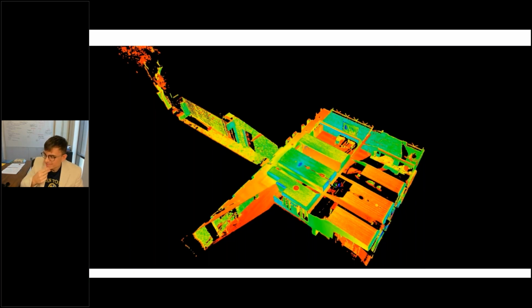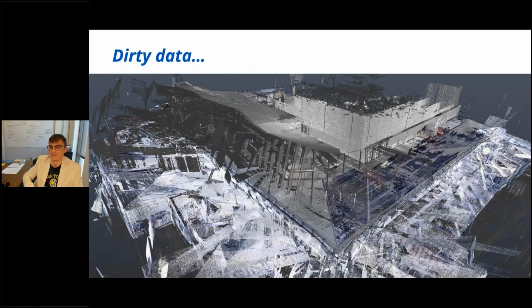And you should know that right now, Recap, a popular software, doesn't allow you to clean scans prior to registration, but pretty much every other software allows for this. And if you're seeing a lot of noise above your facility, you're like, there are no windows or mirrors here, what's going on? It's a good indication that you need to clean your lens.